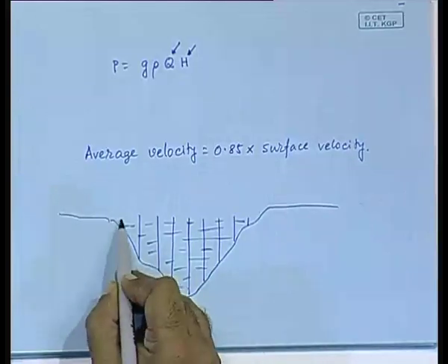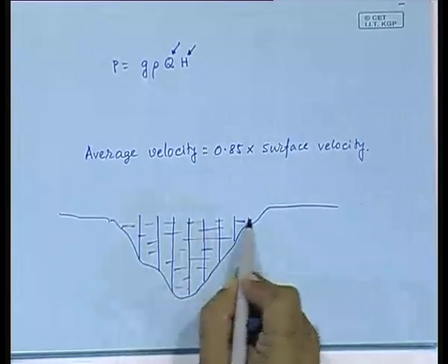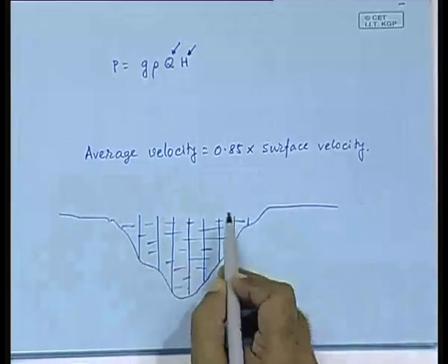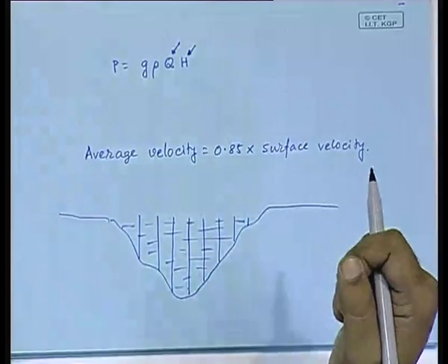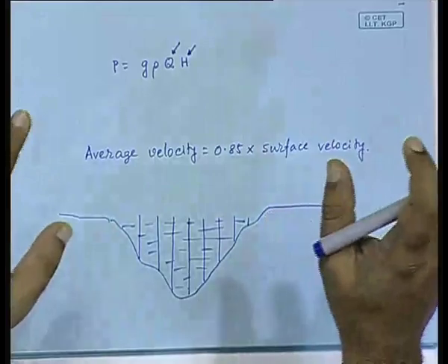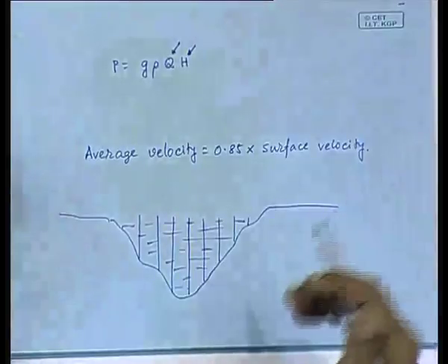So, go to various distances from the shore, start from one side and dip the bamboo, assuming that the length of the bamboo is greater than the maximum depth. Obviously, you cannot do that in the Ganges, right. So, this method will be applicable only in relatively smaller rivers, and then you take a graph paper.